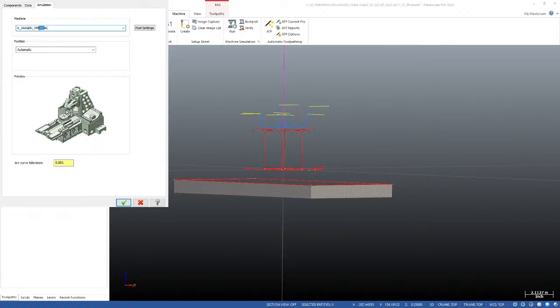So this is a mixed mode configuration machine where we've got a rotary axis on the head that is an A axis, and we have a rotary axis on the table which is a C axis. That's the AC. So it's telling you the default configuration for whatever machine is in the drop down, and they have a naming convention which helps you easily sort it out.